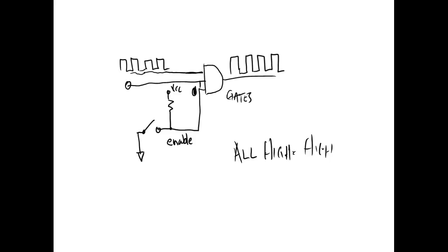As we move through here and start getting to these more complex chips, you're going to see some of them have enable and disable. One perfect example is in a computer. I can't have everybody on this bus we call the data bus all the time. How many things can be on the data bus on a computer at any one time? Well, how do we keep all those guys off of it? Well, we disable them and do what?